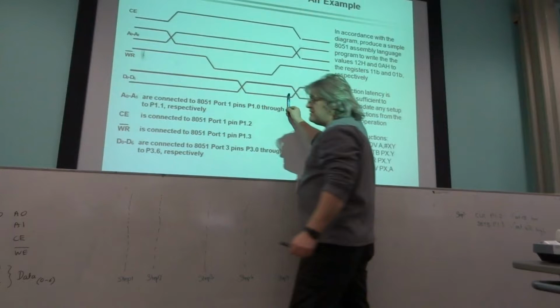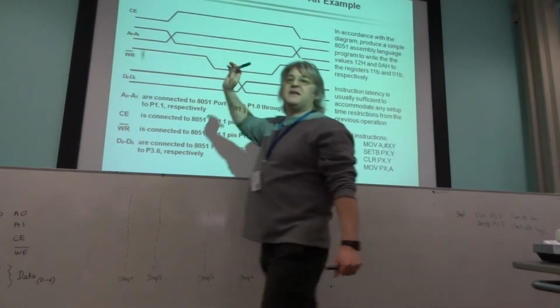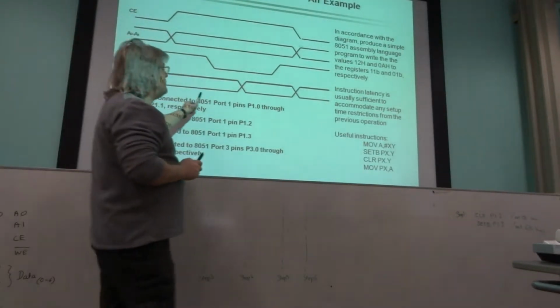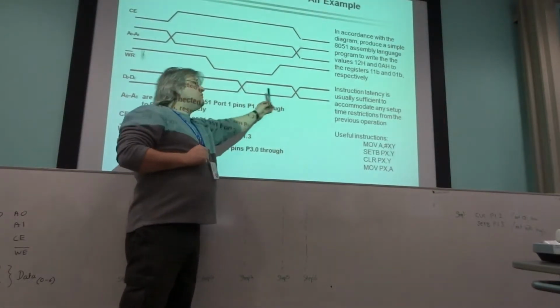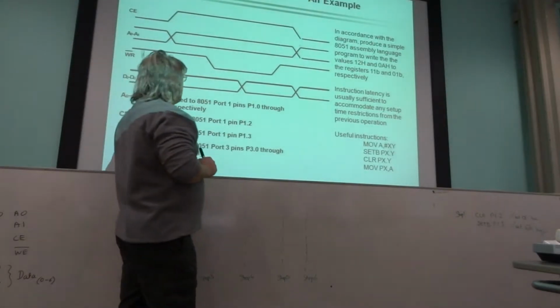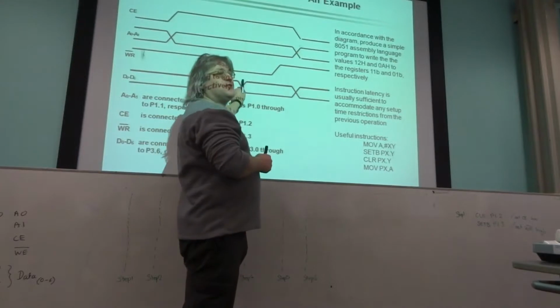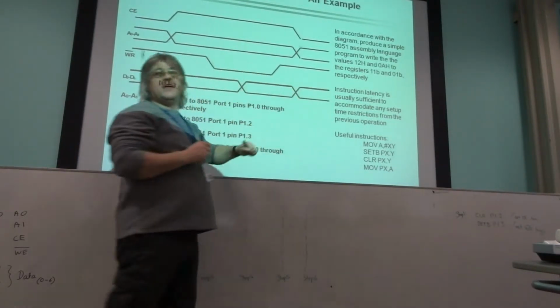The way this is written, if I was to estimate when does data actually matter, the way this is drawn, I would say it's in this chunk here. What we're showing is some kind of initial value here, but in here, whatever the maker of this data sheet has done, they've shown a particular transition here and here and stable within that range.